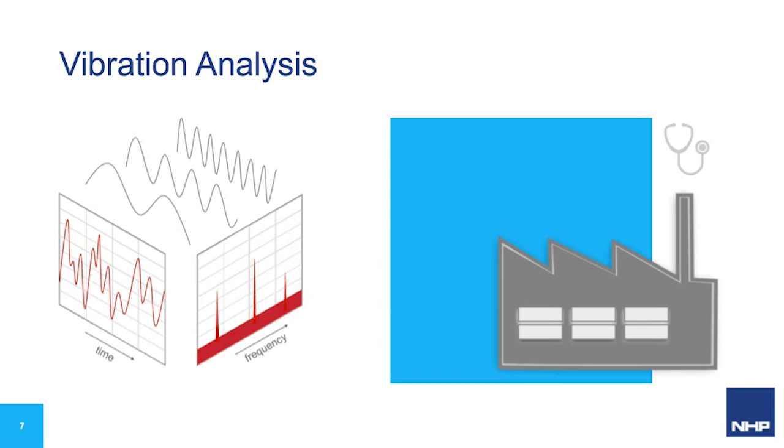Faults induce repetitive impact or cyclic forces at specific, predictable frequencies, and these are related to the machine speed, mechanical, and/or electrical attributes. So to understand what is causing the vibration, we can simply monitor the fault indicators. Fault indicators are the magnitude and sometimes the phase values of specific frequencies of vibration that are caused by mechanical, electrical, or process conditions.